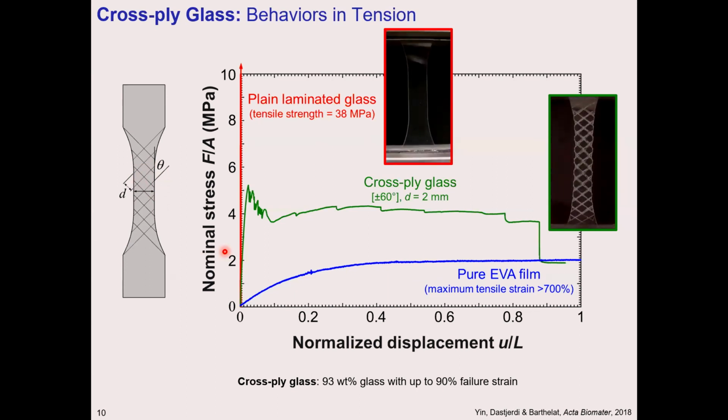But when you pull it, the plies actually separate, getting distant from each other, and there is also shear deformation of the interlayer. When it deforms, it will have some plastic deformation. Once it has plastic deformation, it becomes a little milky, and that milkiness is what you see.